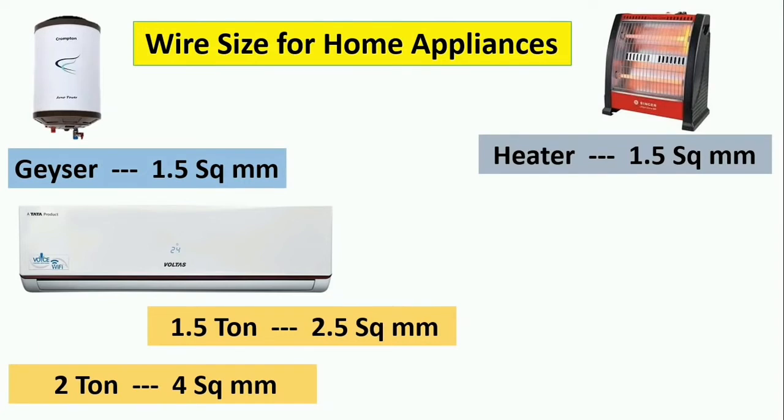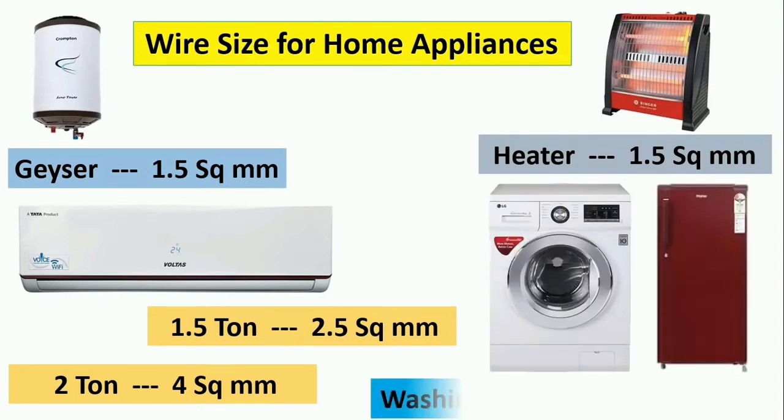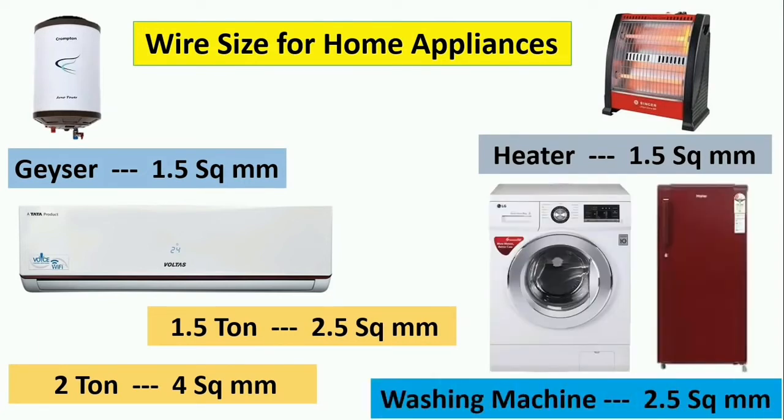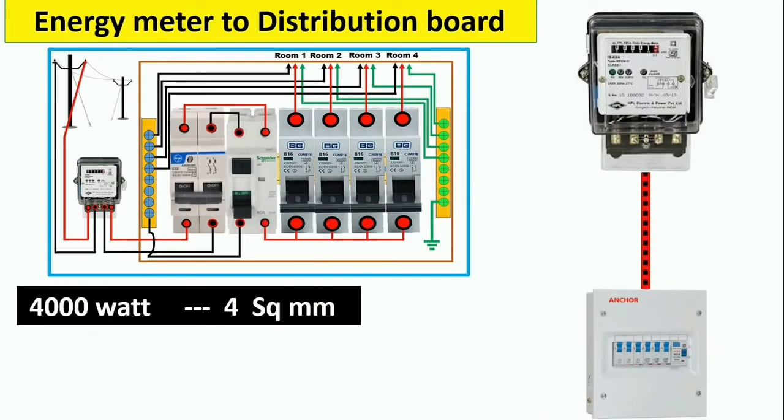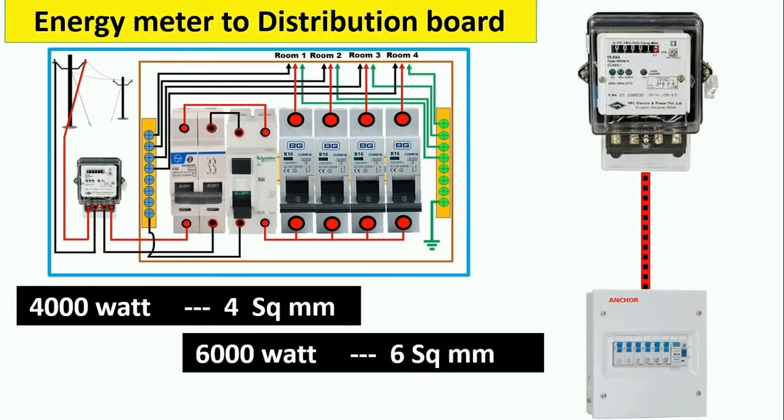So it is necessary and very, very important that when you want to make certain installations at domestic homes or industrial places, you take into account these cable variations in terms of diameter and how useful they are from level to level. How useful they are at different stages, say from the meter to distribution boards or distribution board to the main load. You want to be very, very careful about the kind of cables you use.